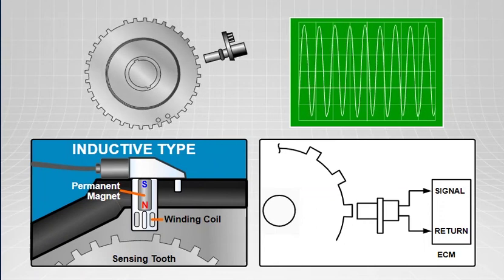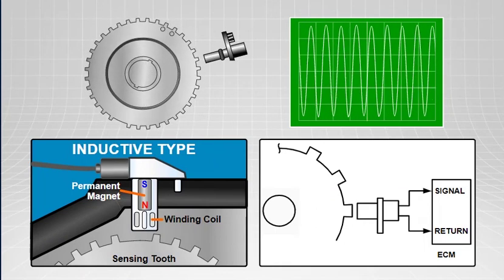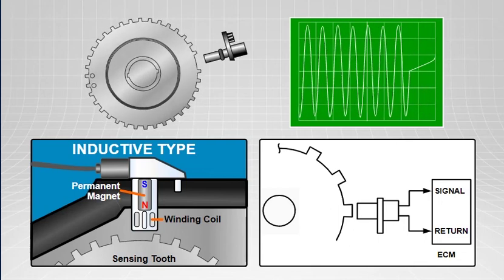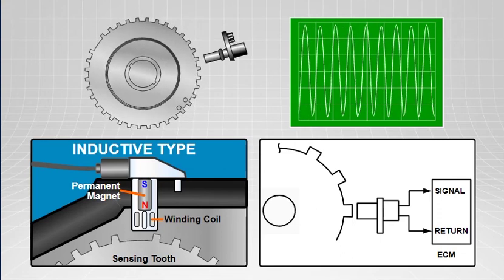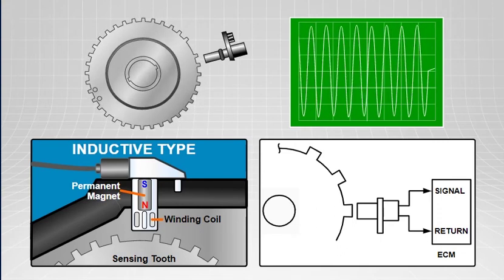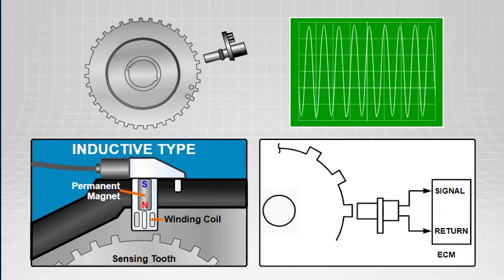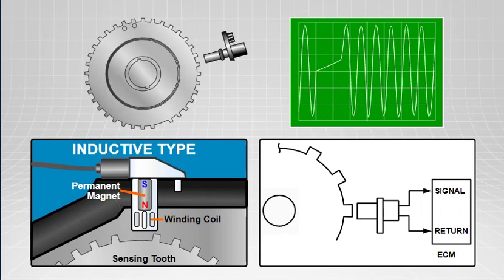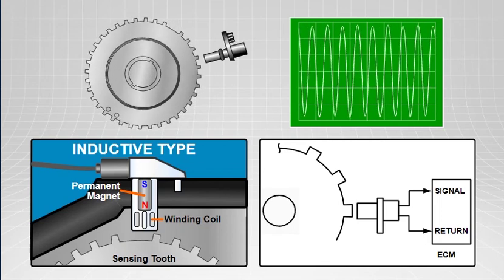The crankshaft position sensor, or CKP, measures the engine RPM. It also may detect when the cylinder is on the power stroke. Similarly, the camshaft position sensor, or CMP, indicates camshaft position for use in valve timing. One type of wheel speed sensor generates AC signals and indicates vehicle speed. The control module uses changes in the signal to determine position or speed.